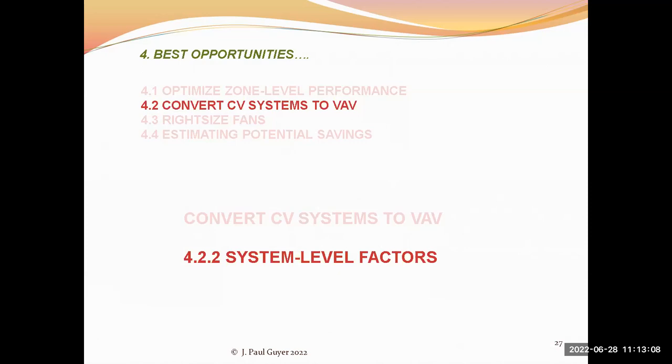If you have an existing dual duct or multi-zone system, you need to determine whether the existing hot and cold dampers are controlled by one or two actuators. Converting these systems to VAV usually requires two actuators, so that the hot and cold air supply can be regulated independently.